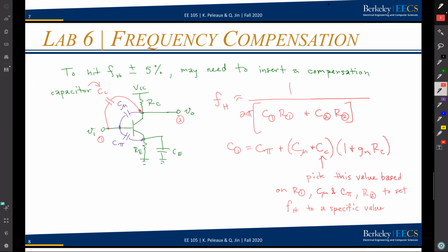And so to do that, what you do is you add a pole at a low frequency so that by the time you get to your other, higher frequency poles, if you go through two poles, you'll have a 180-degree phase shift. And so any negative feedback will actually get flipped and be positive. But if your low frequency pole is low enough, the gain at that point where your phase goes to 180 will have actually dropped below 1. The only case where I'm concerned about positive feedback is if the gain is bigger than 1, because every time a signal passes through the loop, it'll add because there's positive feedback, but it'll also grow because the gain is more than 1. If the gain is less than 1, sure, it'll be adding, but every time that component will get smaller and smaller, so it'll be attenuated.